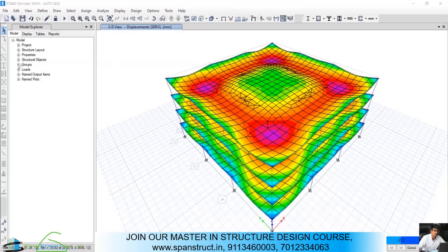So right now in the project you are seeing, we are applying every load at once. You can see the dead load, slab load, everything is applied. But when a real structure is built, it is not made like this. A real structure is made first floor, then second floor, then third floor, then fourth floor. So your time-dependent properties and your loading will also change accordingly. How can you account for these things and be more practical about it?